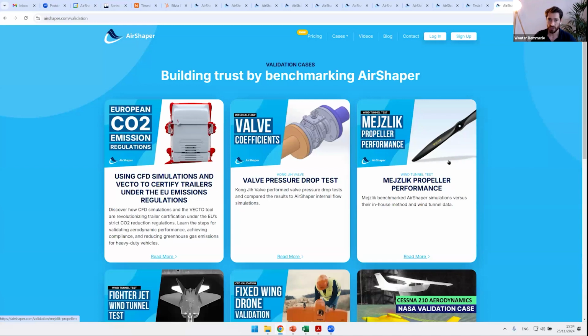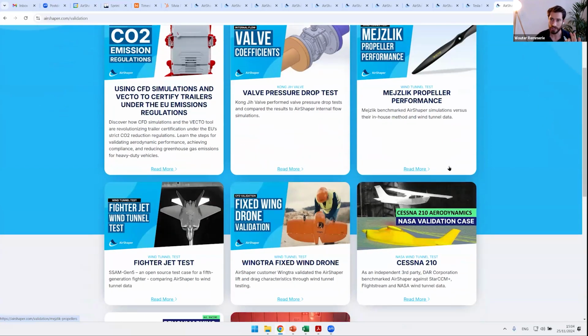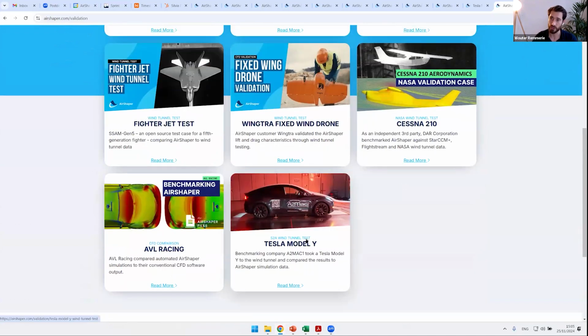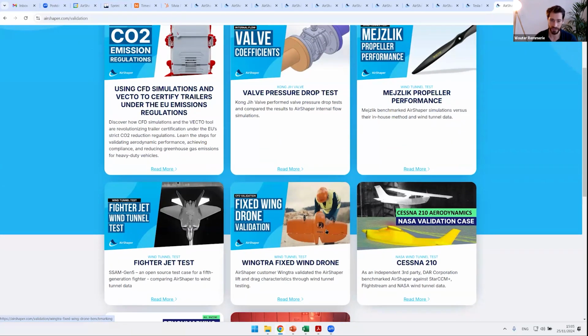The nice thing using this adaptive mesh refinement is that whatever object comes in, we will automatically tune our mesh to the specific flow pattern around that object or through that object, even if it's a pipe flow simulation and so on. Which means that without modifying anything to our simulation, apart from the fact that you can toggle the use of layers on and off, these cases have all been made using the exact same set of equations.